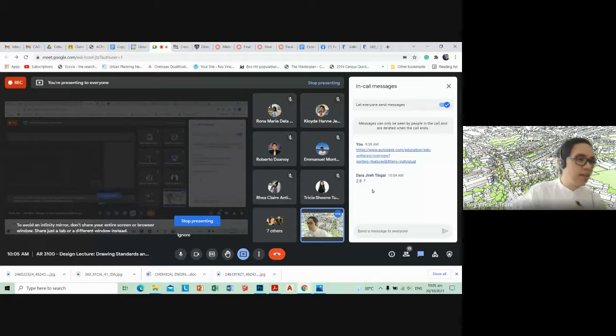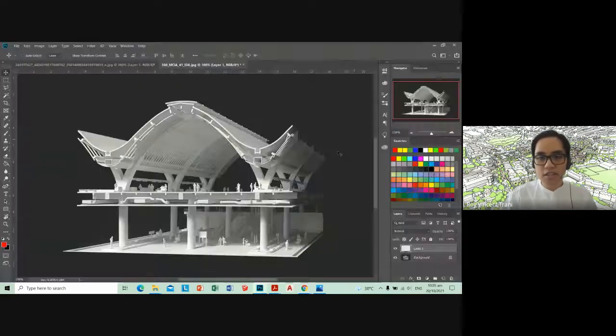Okay. Nice. So it's around 2.7. This is also applied everywhere. Even in Sydney, we had 2.7. The reason for that is so the ceilings don't get too low, but at the same time, the reason why there's a chance that the ceilings will get low is because that's where the utilities are in most buildings.